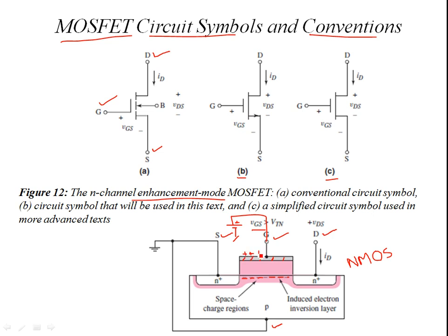The metal is going to have positive charges, and the bottom plate of the MOS capacitor is going to have negative charges, which you see over here, okay. Because this negative is going to come over here, and it's going to attract some holes at the substrate body, down at the substrate or the semiconductor bulk body.